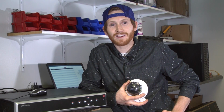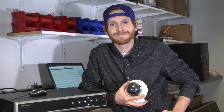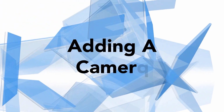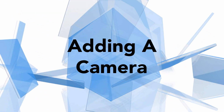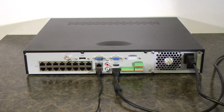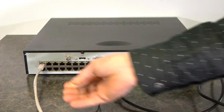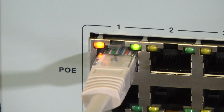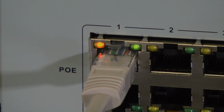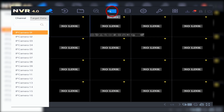Now that we have our NVR set up and configured, we're ready to add our IP camera to the system. We will now plug our camera into port 1 on the back of our NVR and wait for signification of connection with activity lights. As our camera is powering up, on the NVR home screen, we'll select the camera icon at the top of the screen.